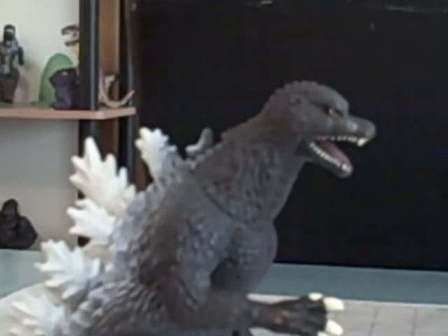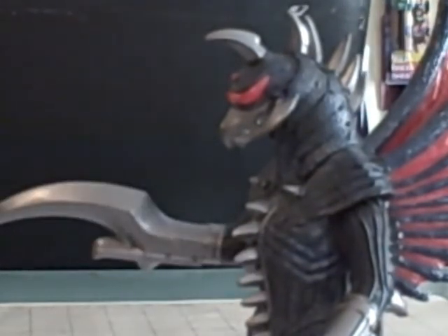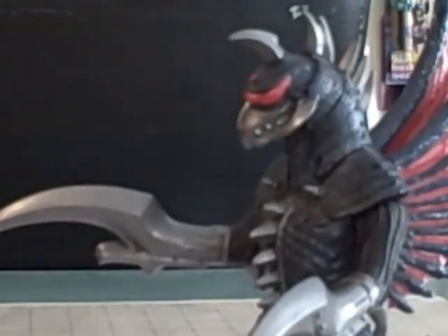What's a wheel and axle? Well, you see, Godzilla, a wheel and axle is a simple machine that actually has two parts: the wheel and the axle. You see, the axle goes through the wheel so that it can spin around. The mechanical advantage of a wheel and axle is the ratio of the radius of the wheel to the radius of the axle. You could also increase your wheel and axle speed by applying the input force on the axle instead of the wheel. You see, the increase is computed like mechanical advantage. This combo could increase the speed 5 times.